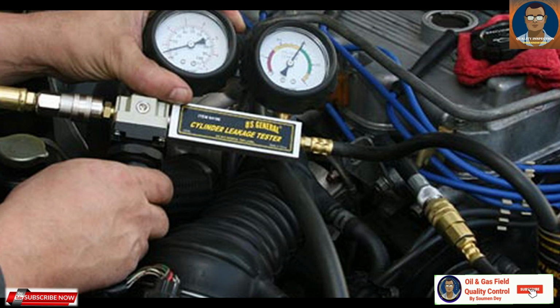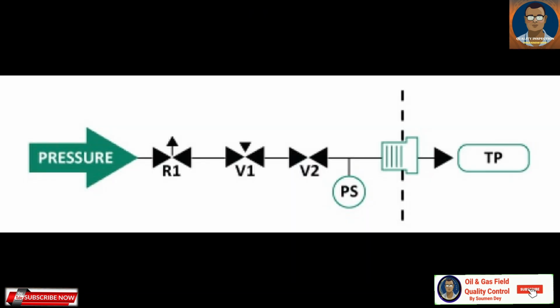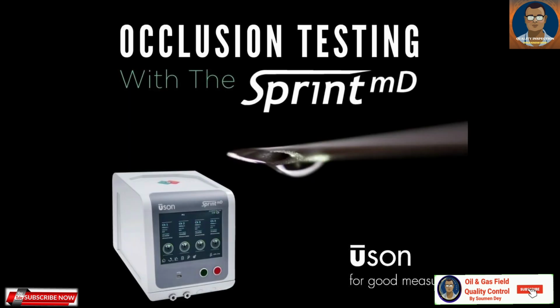Pressure crack. The leak test method is used to identify weeping in valves with a downstream sensor monitor. Pressure or vacuum. This leak test method uses pressurization of a test object and a reference volume. If a leak is present, the difference between the two will decrease. The process is fully automatic. Occlusion. This leak test method identifies obstructions in the flow path of a gas to identify defects that are causing leaks.